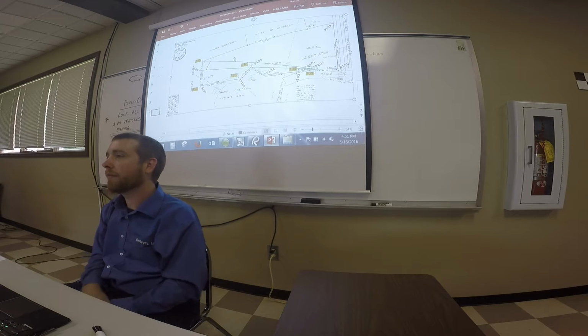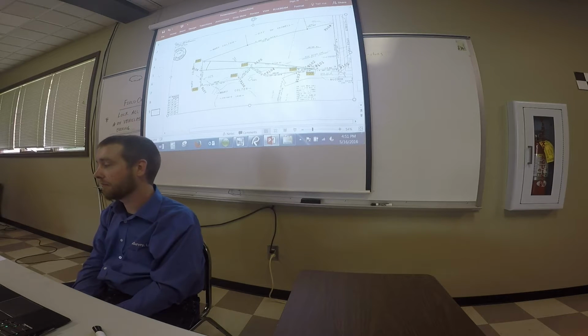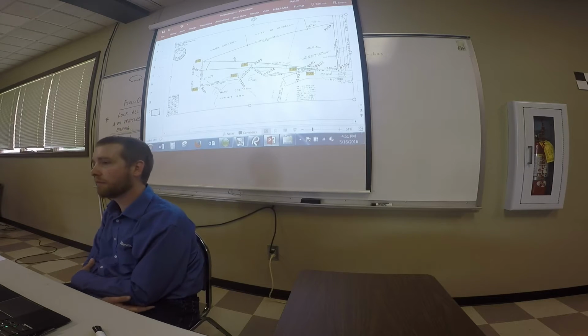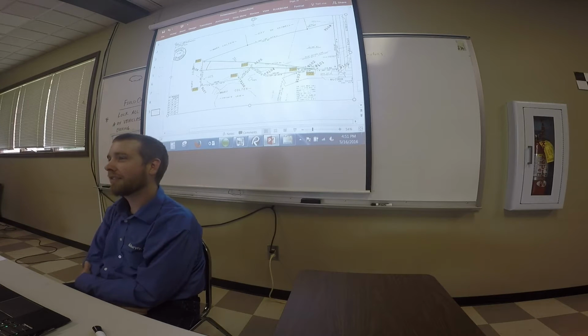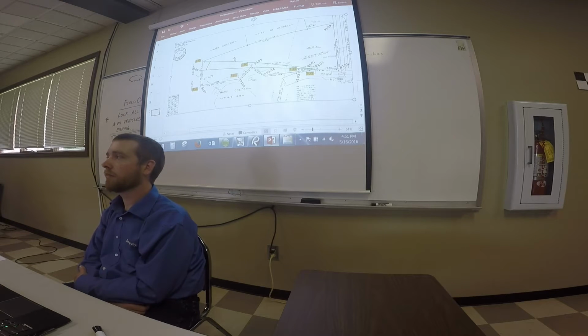Okay, so conversation here. When would be appropriate to choose doing this translate rotate function versus what we discussed previously? Because you need to understand when should I do one versus the other? Okay, I'll answer. Translate rotate you want to do when you haven't found any pins at all. Well, you're going to have to find something. You have to find at least one, or you have to find some. But you want to compute points if the project manager didn't give you any stakeout.